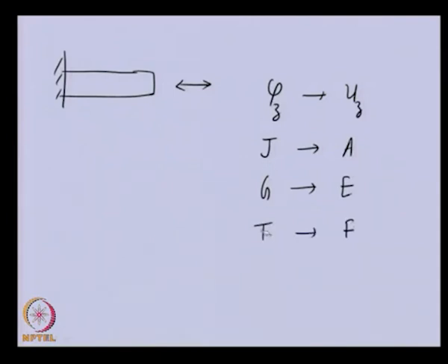So, these will be the changes in the equation of motion, and otherwise the analysis is exactly the same. Differential equation, eigenfunction, everything is the same, only we need to replace these variables, then we can analyze the axial vibration. We will not be repeating the axial vibration analysis here, but just trying to show the analogy.